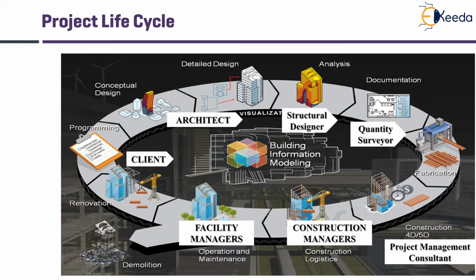Once these building elements are shipped to site, the BIM model is used by construction managers to plan and update the construction logistics. Also, the planning person at the site during the construction phase will update the elements that have been received and installed in the project. Thus, the schedule of the project is also getting tracked.